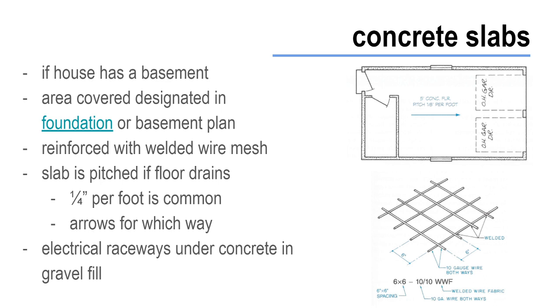And it's usually done by area, not giving the thickness of the concrete slab and any reinforcing steel to be used. To help the concrete resist minor stresses, it's usually reinforced with a welded wire mesh. Welded wire mesh is sometimes abbreviated as WWM in drawings, or WWF for a welded wire fabric. The specifications for that can all be found in building codes.